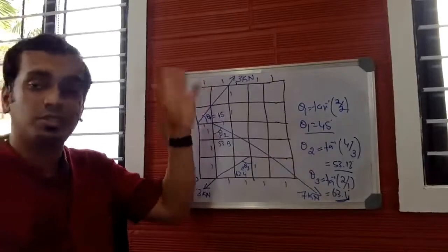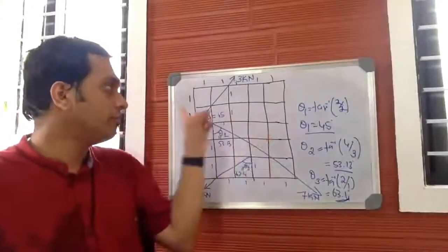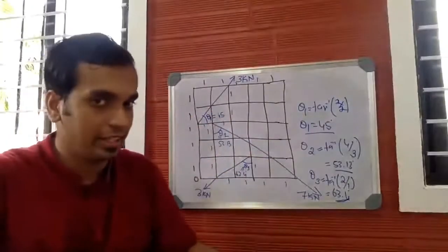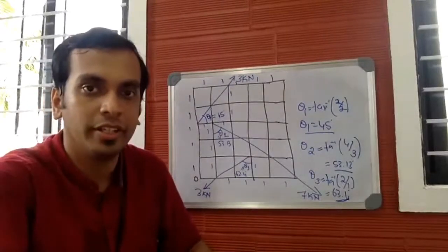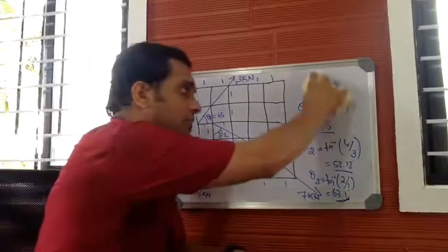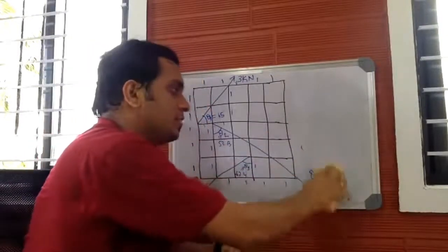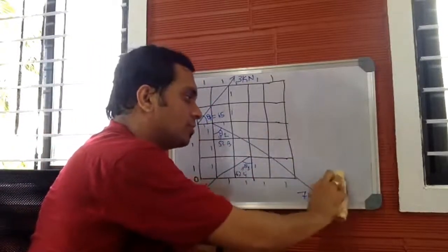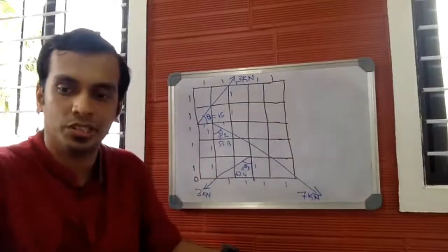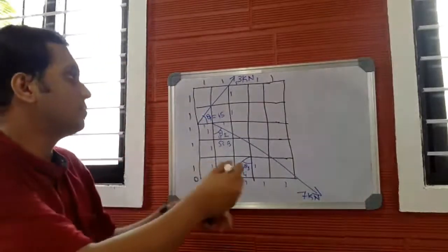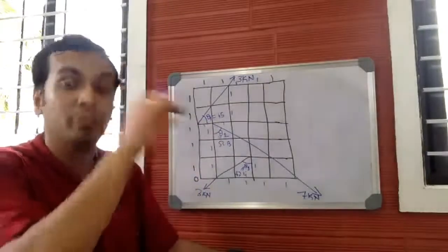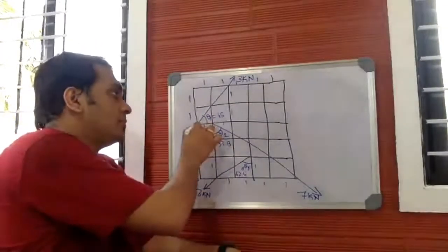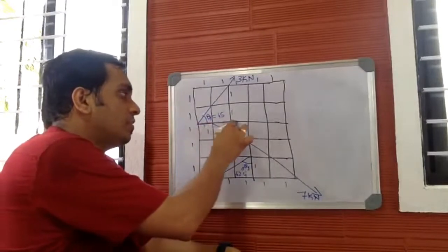So you can use this data, in the sense, side of each square measures 1 meter, to find the angles, which will not be given in the problem. You'll be finding the angles. Once you find theta 1, theta 2, and theta 3, you can easily resolve all the forces into their horizontal and vertical components, is it not? So what's the horizontal component? Make sure that you draw the horizontal and vertical components exactly at the point of contact, the point of application. So this is the point of application. Now this will be the horizontal component.